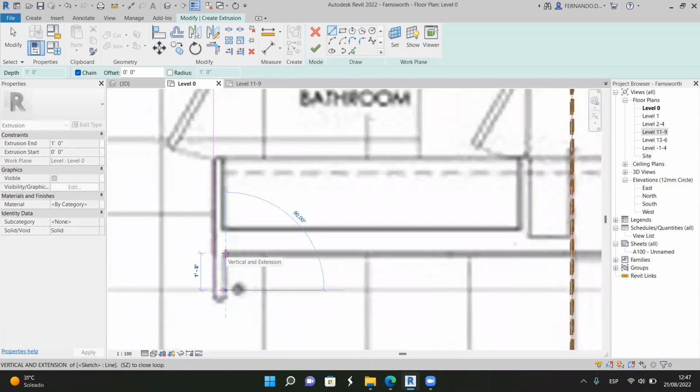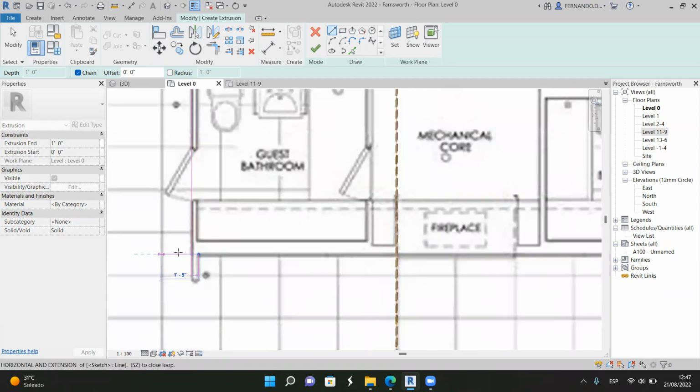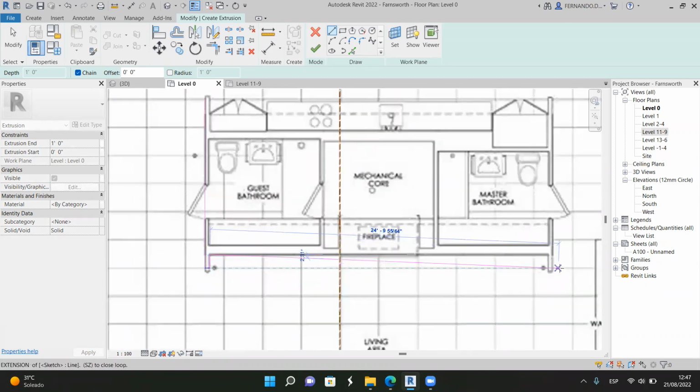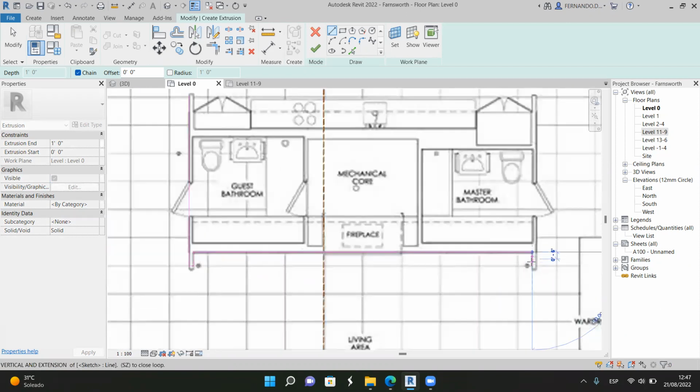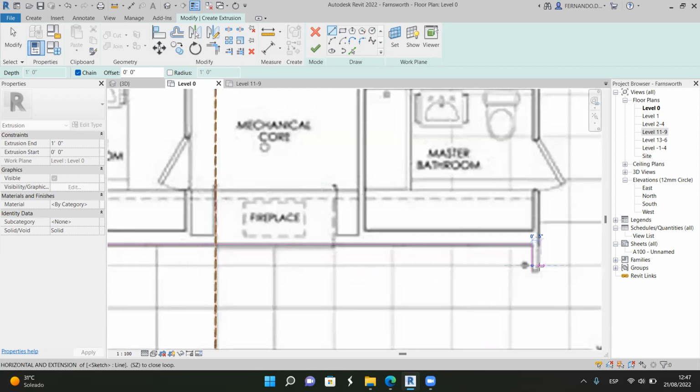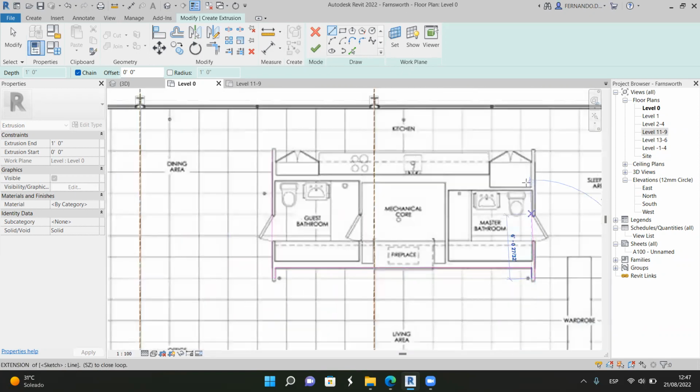And if I select that this is 1 foot, trying to round things up, then here, and then, yeah, you see that Revit knows that there's another line, and this dashed line shows up. So that means that those things are aligned. So that's fine. And then what's the distance of this? 4 inches, the thickness is 4 inches.